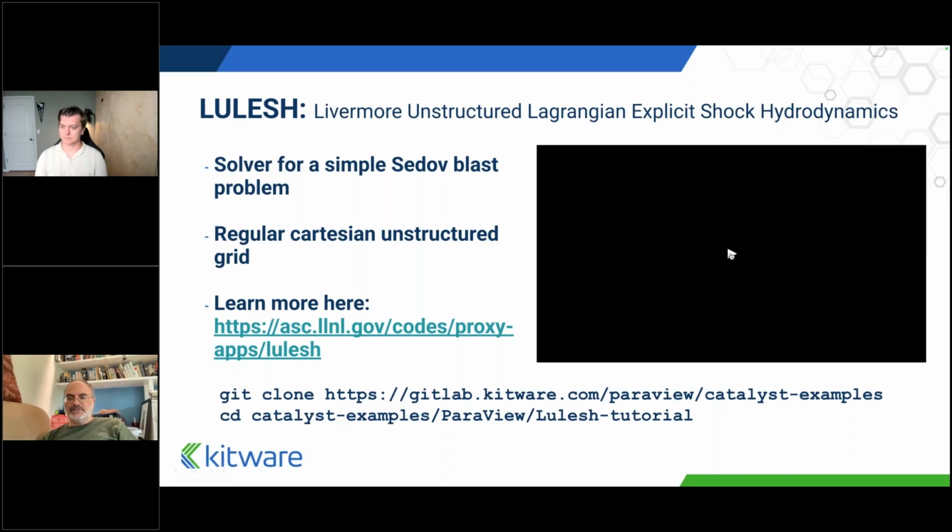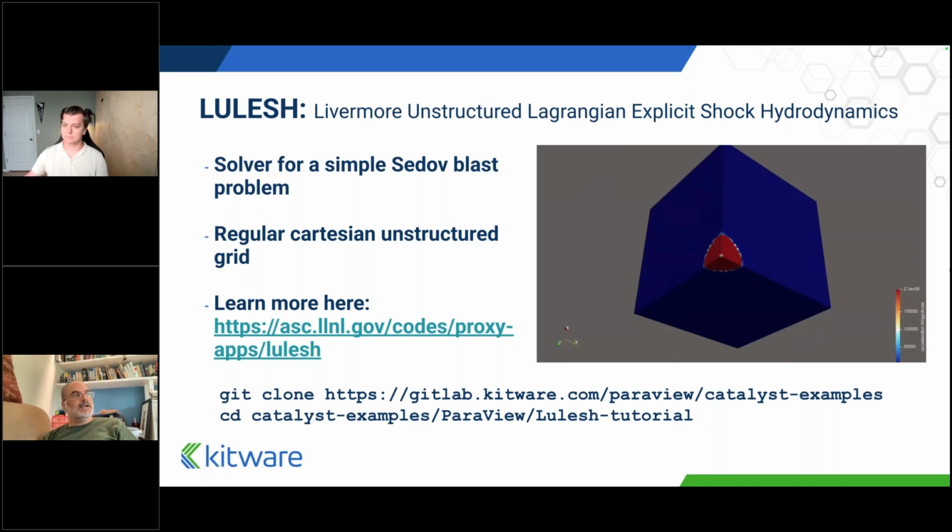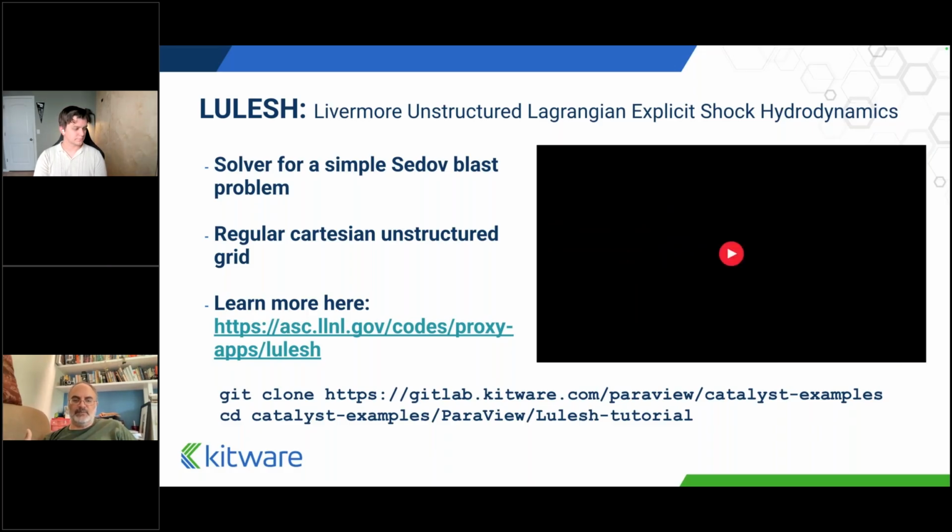I would say yes, that constitutes an in situ workflow. However, since you're already in Python, there is no need to use Catalyst. You can actually directly invoke ParaView Python by importing ParaView into your Python environment, passing data to it, and calling it. And the passing data may get somewhat involved. In that case, actually using the Python interface of Catalyst may make things easier in some ways.